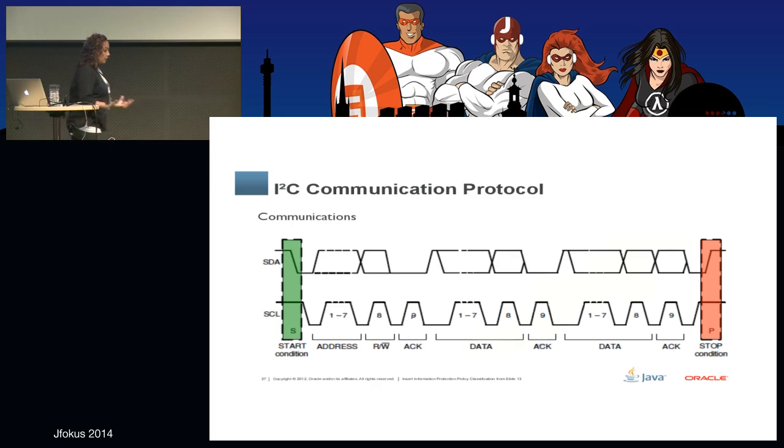Now, you have your I2C device. The device has an address, okay? Inside that device, normally you have registers. For example, my device has a lot of registers, way too many, and it took me forever to understand which one I needed, but anyway, that's a different story. You have a bunch of registers, and sometimes you only need a couple of them. For example, the temperature register, I need that to be able to pull out the temperature reading. So you have to know the addresses of the registers that are of interest to you.